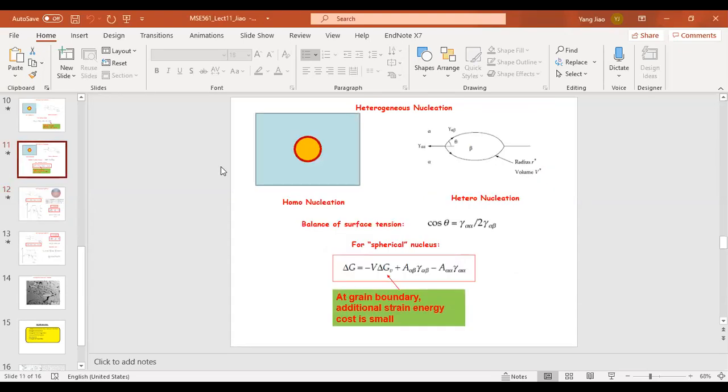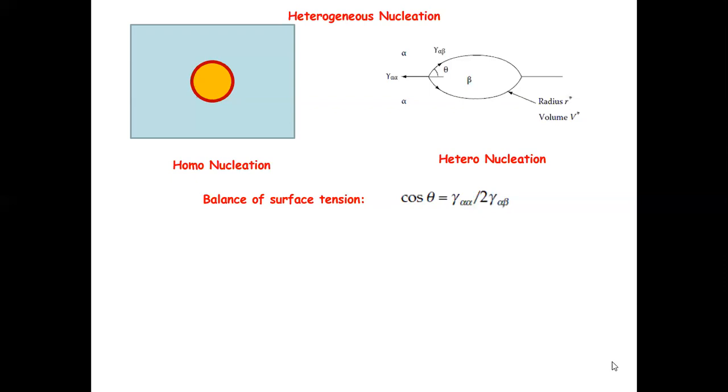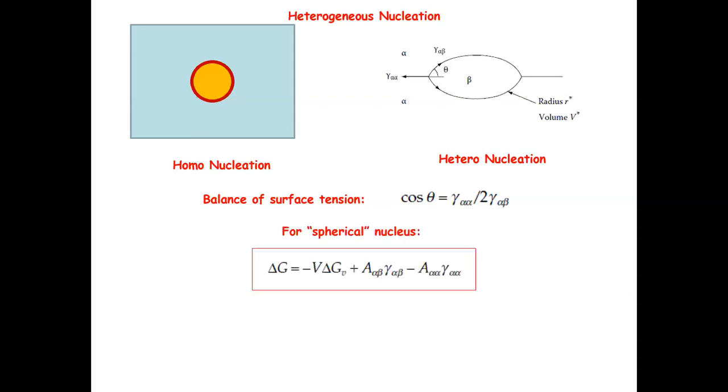So let me continue our discussion on the nucleation problem. In the last lecture, if you still remember, we started to talk about precipitation, and especially nucleation of precipitates. We discussed different types of nucleation and mentioned that growing a secondary solid phase in another solid phase is typically coupled a lot with the defects in the system. We discussed homogeneous nucleation, which means that you insert a secondary solid phase particle in the bulk of a grain of the parent phase. So you have to insert this yellow solid into the blue one, and this causes a huge strain energy, which diminishes your driving force for the transformation.